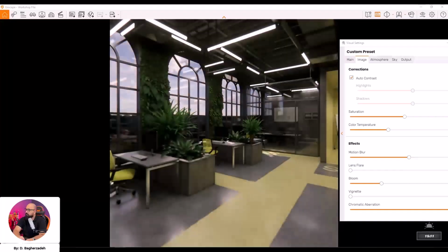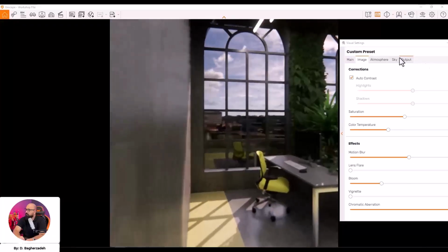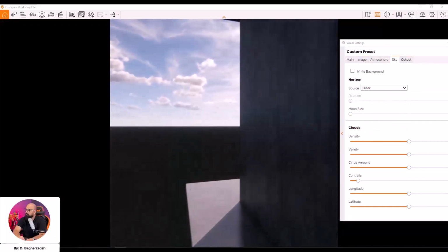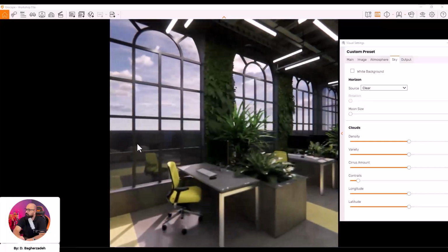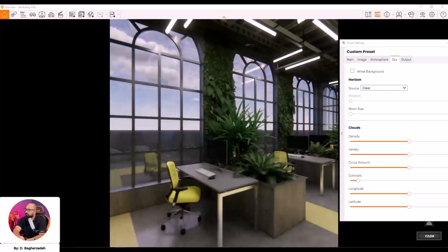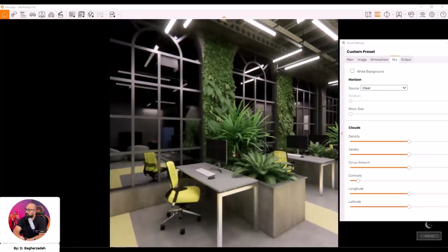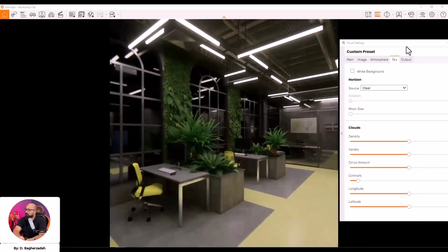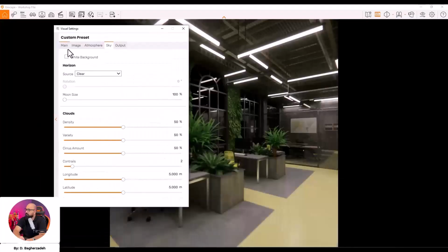If you go with a daylight, with a day view, because of the horizon line, let me show it to you actually. Yeah, because of this horizon line, this area would be completely black. Now, you can do some modeling work outside, but I don't really recommend it. And also, because we want to show the lighting system, the light sources that we set in our model, it's better to use a night view for our presentation.